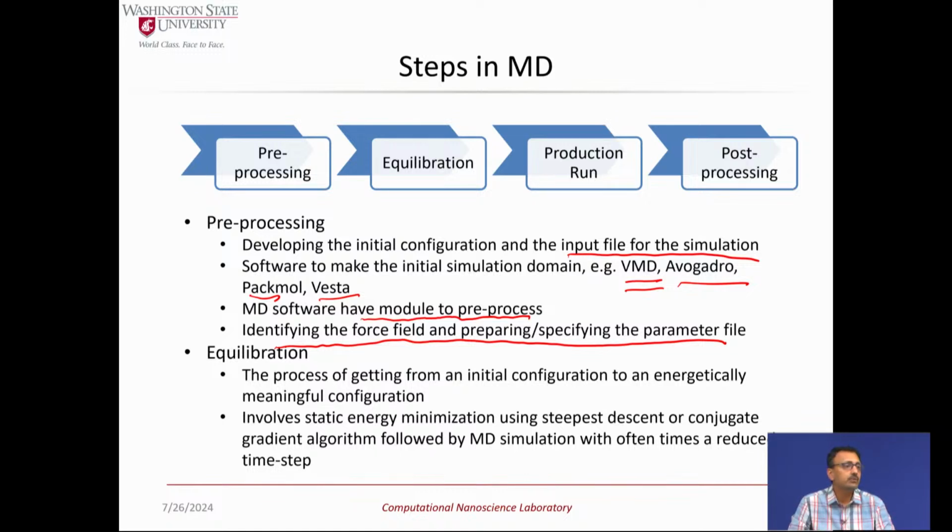As far as the force field goes, no, you're on your own. You have to just make the right judgment, pick the right force field, and make sure that you have the right parameters. There's no tool that can tell you what to do. Same with the input file. But the configuration that you're developing, which is the main part of pre-processing, you can visualize. If you clearly see there is overlap, there's a membrane and polymers are going through it, which they shouldn't, then you have to correct it somehow.